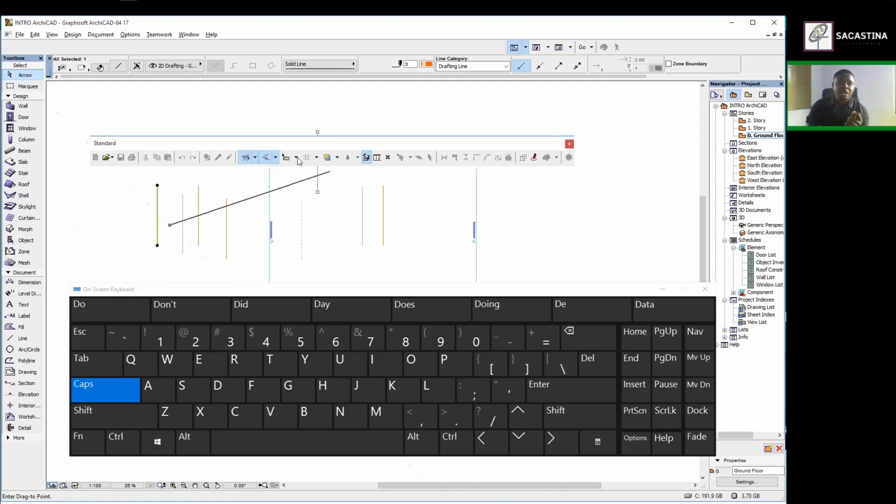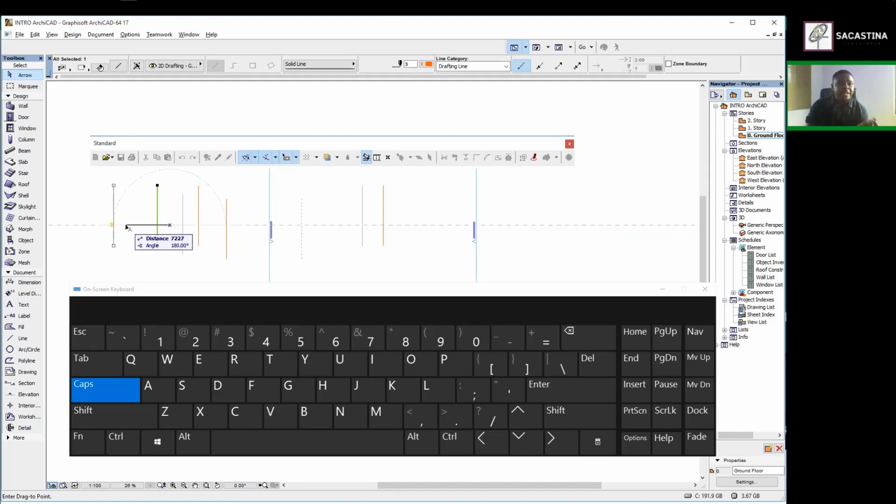While you're still dragging the file, you can actually go with that file and then click on it, and it will bring out your dimension tool for you to input whatever dimension or angle that you want. You type it, and then let's say we are using something around 1.2 meters. We've not set the main perimeter, but we're just talking about the interface. Now you say 1.2 with the same angle, and you click enter, it will go that distance that you wanted it to go. That's what that particular one does.